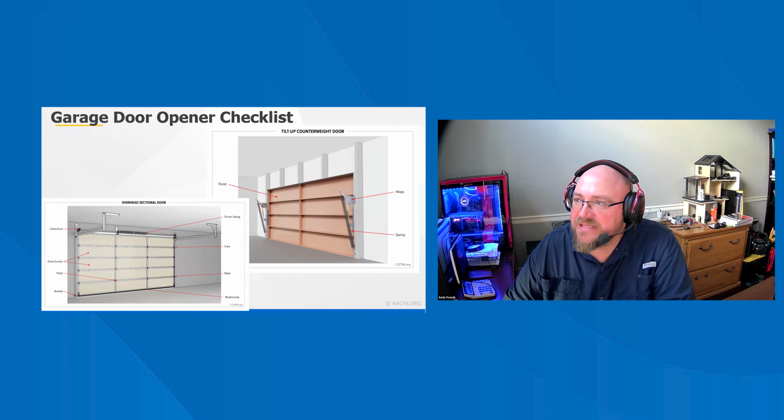Door panels from inside the garage with the door fully closed. Check the condition of the door panels. Check for damage, cracking, denting, bulging, separation of the panels. Check the door panels for indications of fatigue. The door panels should be free of any signs of cracking. The door panels should be free of any signs of separation of materials.